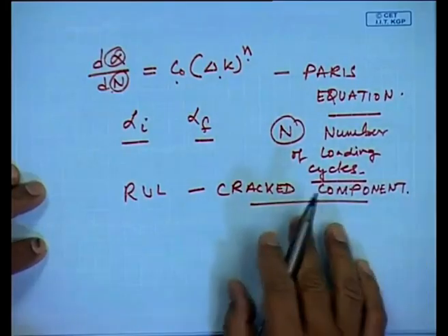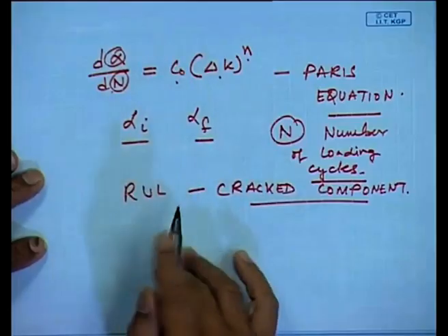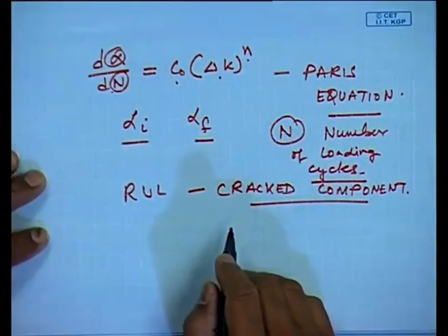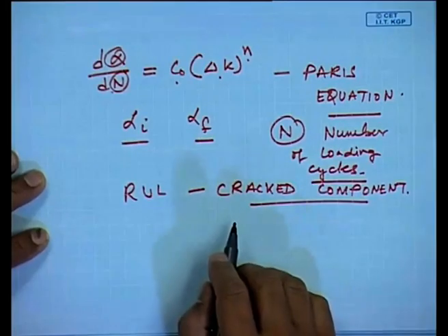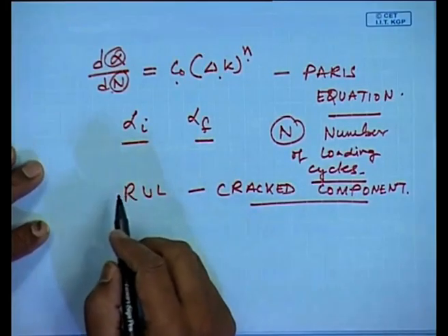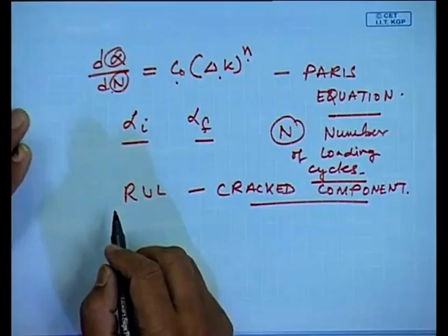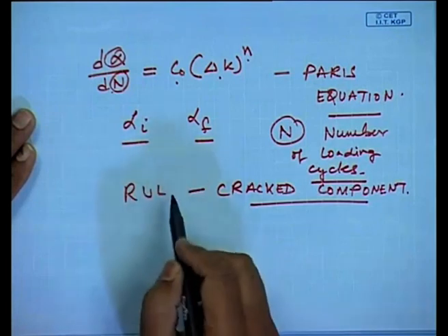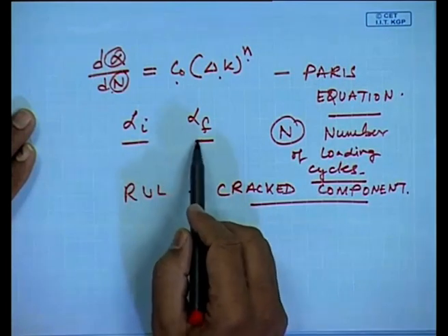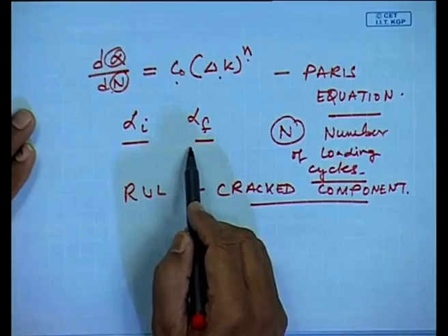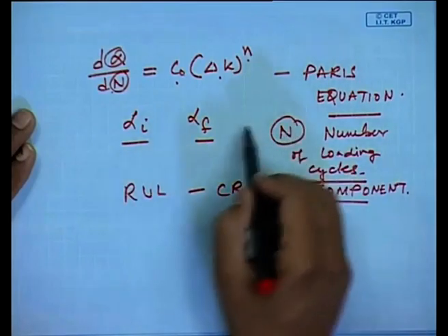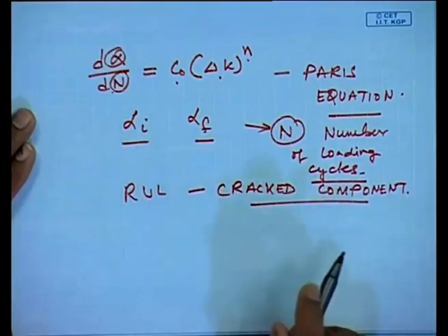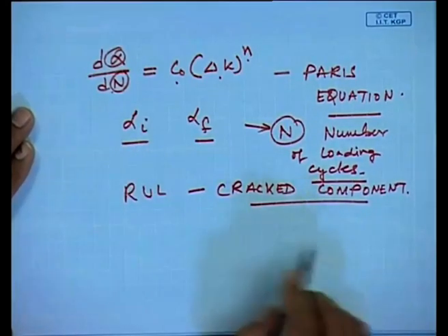This being a basic course, I will not go into details of all this because this will require a lecture on fatigue failure and fatigue fracture mechanics, but I just want to mention that such techniques are available for crack growth development. Once we know the final crack length which our machine can be subjected to, we can estimate the number of loading cycles and thus know the remaining useful life of the machine.